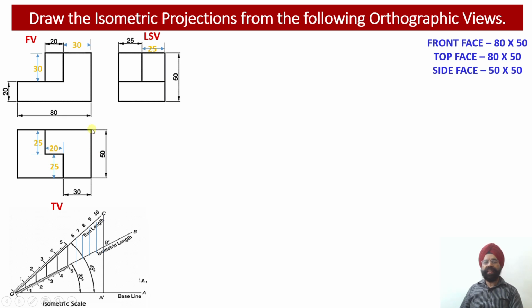Now, if I look at this element number 2, what do I observe? Number 1, this element which is shaped equal to 7, it is a single element. From the top view, I observe that it is a single element. Second thing, I know the shape of this segment, that is element 2, from the top view. Then from the front view, what information do I get? The height of this segment is equal to 30 millimeter. Please check, height of this element is equal to 30 millimeter.